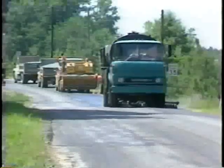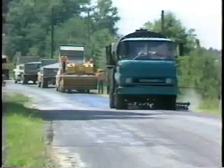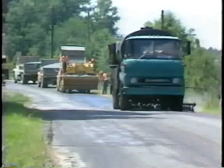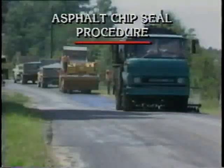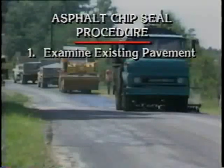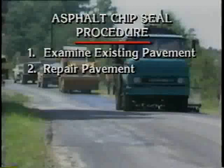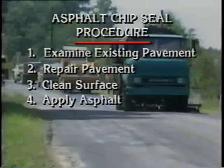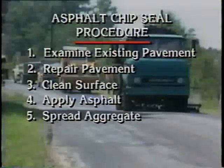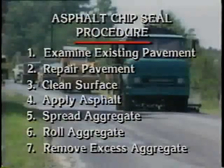A 7-step procedure will be presented for performing asphalt chip seal operations. By following this procedure, an effective asphalt chip seal can be installed. The asphalt chip seal procedure consists of: 1. Examine existing pavement. 2. Repair pavement. 3. Clean surface. 4. Apply asphalt. 5. Spread aggregate. 6. Roll aggregate. 7. Remove excess aggregate.